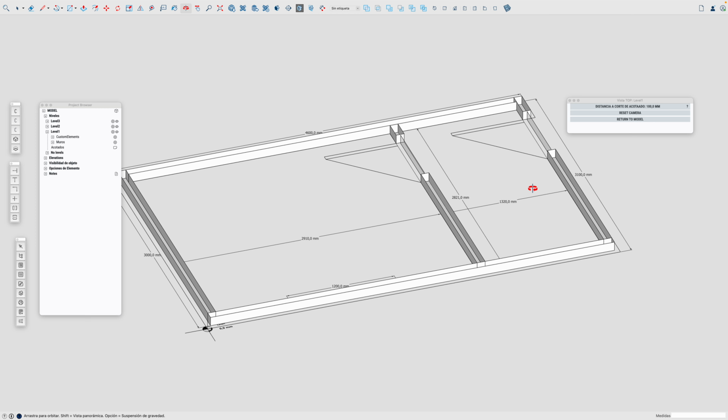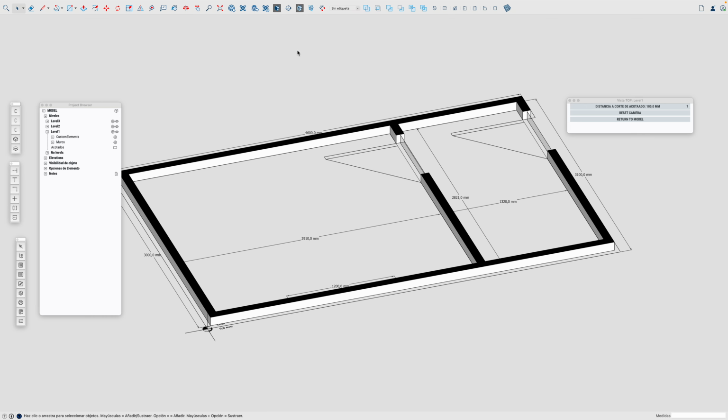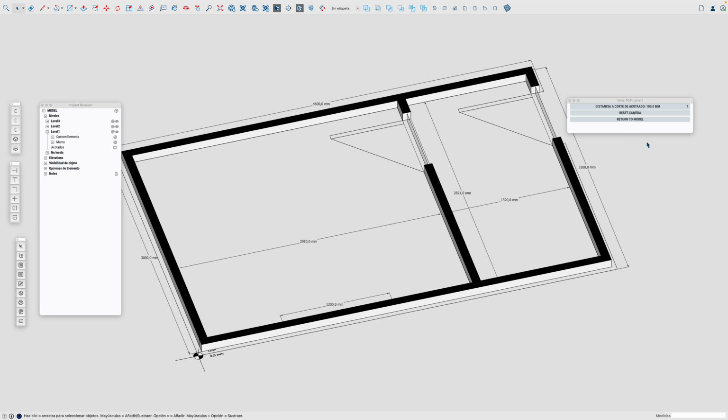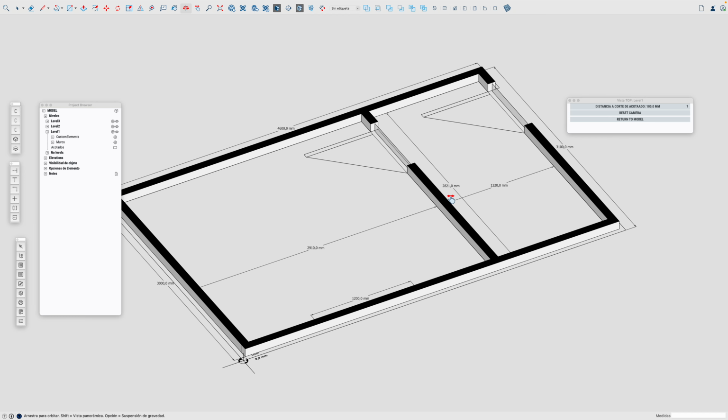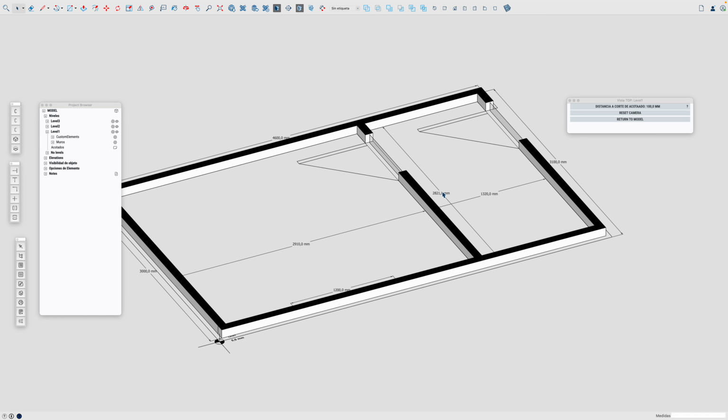to the geometry, you see, and we can also show the cuts as solid as well, I don't have that now here. So you can see this is a section, and we create the section and place the camera on top, so you can easily add dimensions. And that's why you got these commands here.